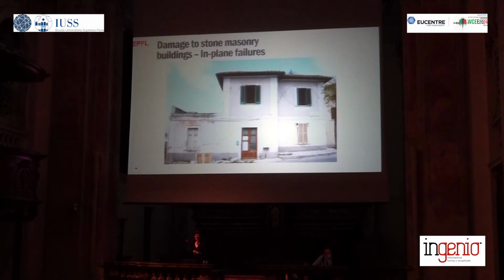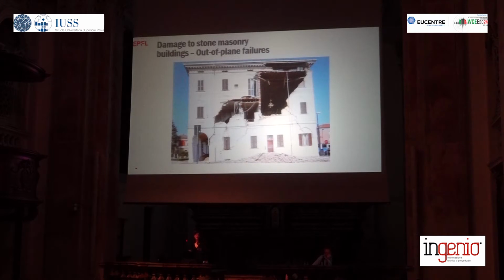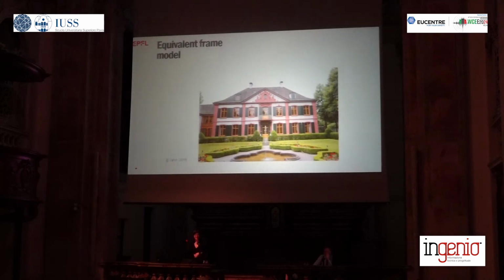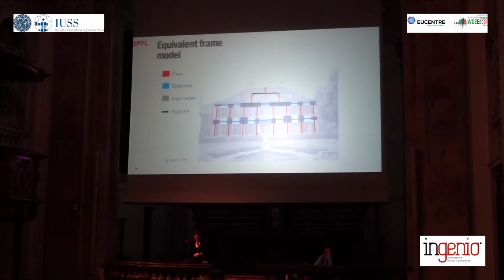As you know, in stonemasonry buildings we have of course in-plane failure modes, but because often we also have these timber slabs that are very poorly connected to the walls, we also have a lot of out-of-plane failure modes. So for the analysis of these buildings, we often use equivalent frame models, which were very much developed here, in particular by Andrea Penna during his PhD thesis. The piers are modeled with vertical elements, the spandrels with horizontal elements, and then the rigid nodes, and then we end up with that frame.